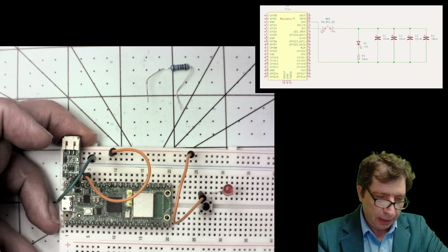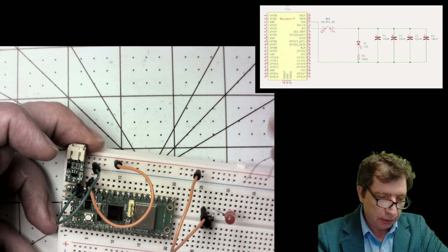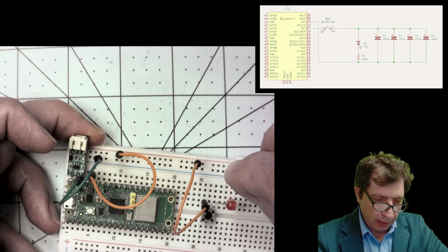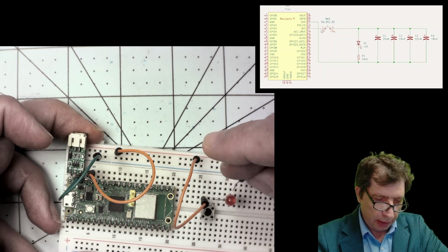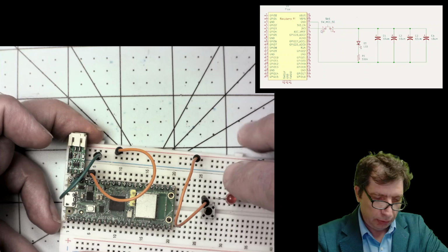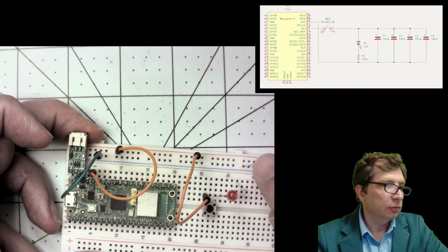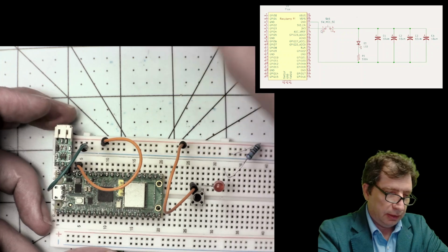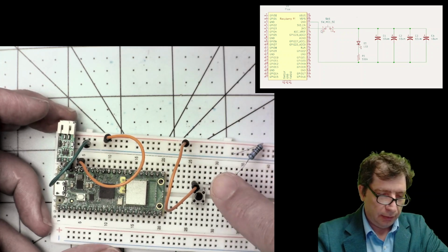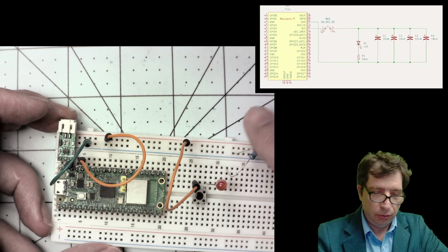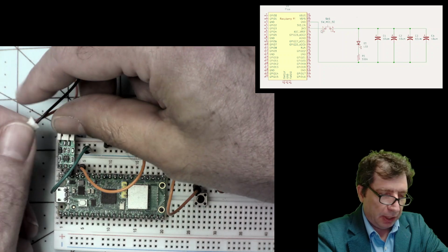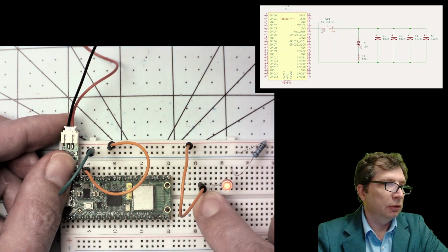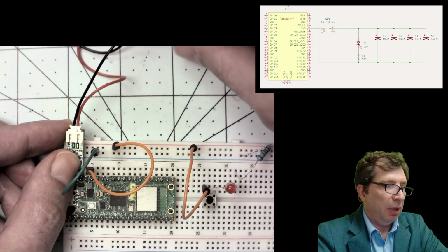And then our resistor is connected between the LED and ground, so we can do it like this. So my diode is connected through the resistor to the ground, so we can check if that part of the circuit is functioning. So we are debugging it slowly. So that part works. Disconnecting the power